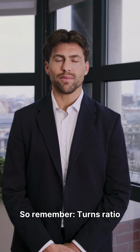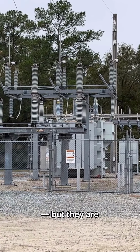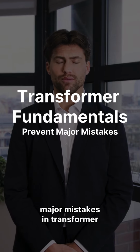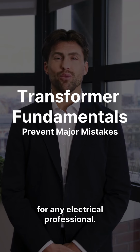So remember, turns ratio is about coils, and voltage ratio is about voltage. They are usually equal, but they are not the same thing. This distinction is vital. Understanding this can prevent major mistakes in transformer selection and design. It's a fundamental concept for any electrical professional.